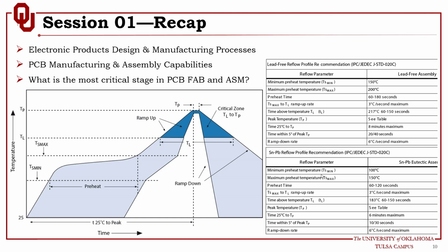And if you have to use it, as I mentioned in the first session, in the prototype stage where I produce 1 or 2 boards for sampling, I use leaded solder with very little exposure to the soldering process. So I use a mask and I put it in a special room with vacuums and filters and stuff like that, because it's easier to replace a component in the prototyping stage if I need to fix something. But this is 1 or 2 boards and it's not meant for customers, it's just in the lab. So I have full control over that. But once we go to mass production, and this goes to the customer, we use lead-free solder.